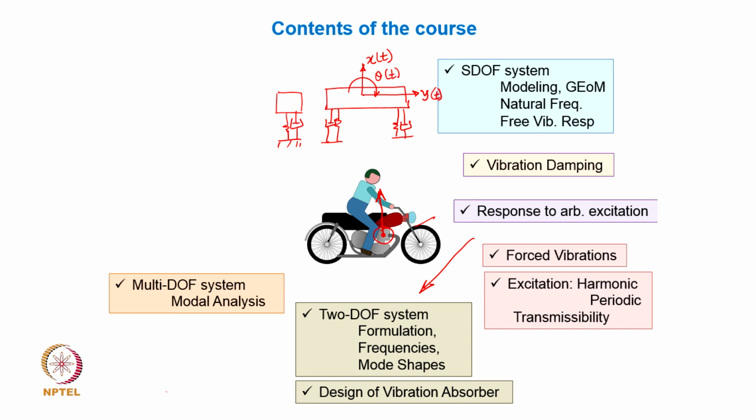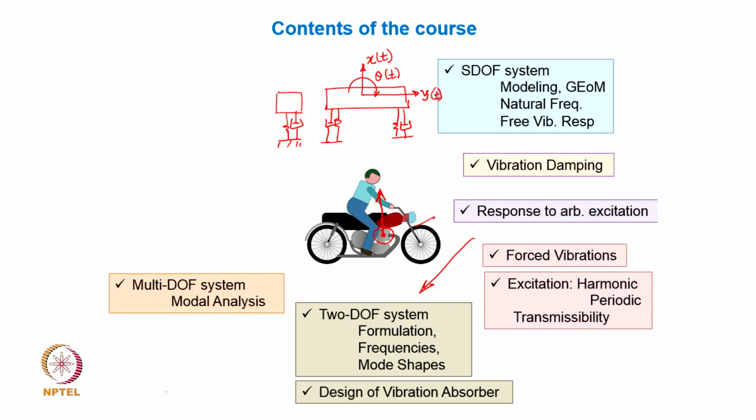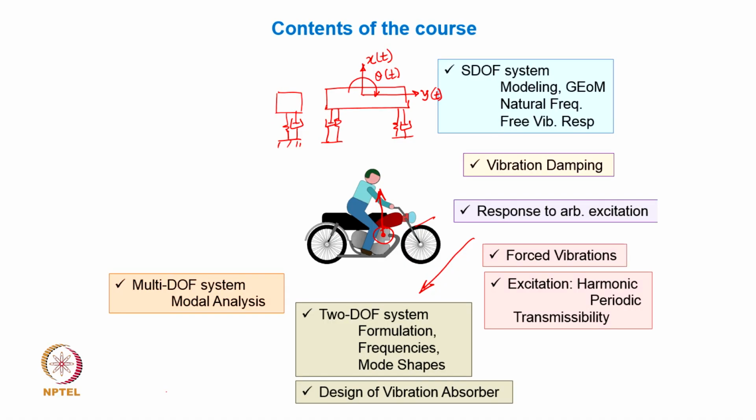In this particular topic, when the degrees of freedom substantially multiply and increase significantly, the efficiency of the solution process is important. Typical discretized numerical models, such as those done through the finite element approach, will have several thousands or several tens of thousands of degrees of freedom, and solving them becomes a challenge. So, modal analysis is an approach which helps you to efficiently solve these matrix equations, and we shall see how modal analysis as a process is applied to a multi degree of freedom system and eases the solution process and the computational complexity of it.